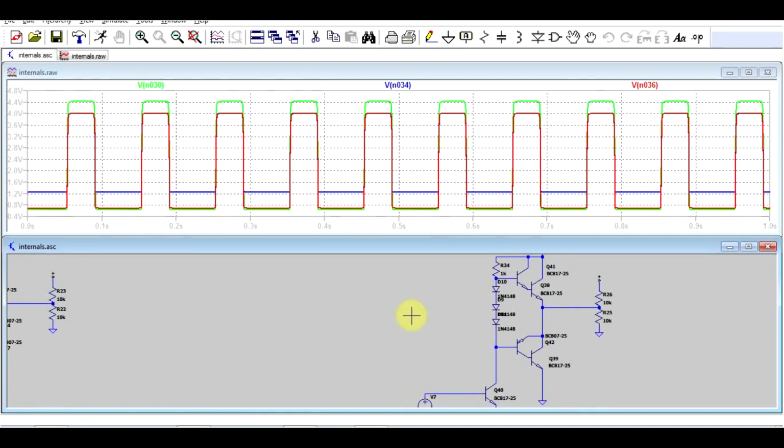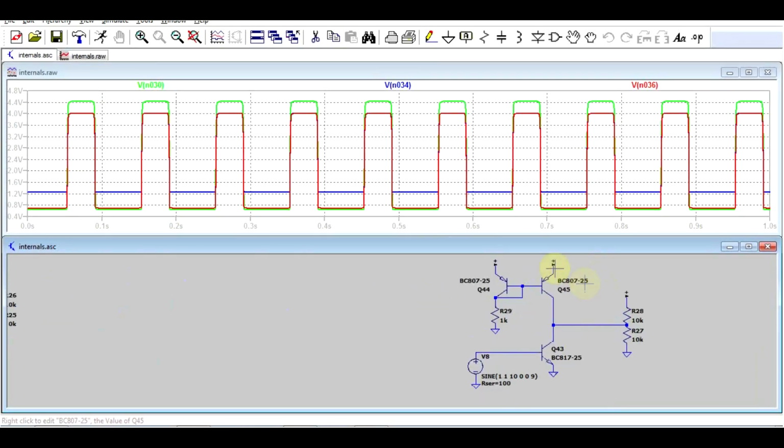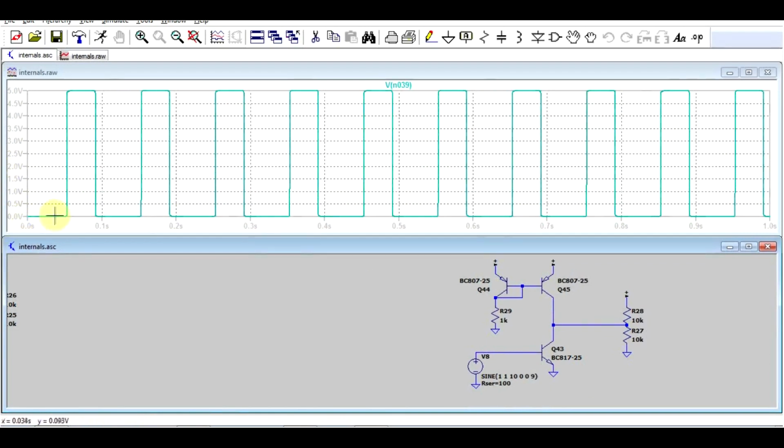Well, the simplest way of getting rid of either one of the limitations or both is to use this sort of output stage, the Class A output, in which we have a low side transistor and on the high side we've got a constant current source. In this case, our output will go from one rail to the other. No limitations, only given by whatever saturation voltage we got on either of the transistors. So with this sort of stage, although highly inefficient, we can get a rail-to-rail type of operation.